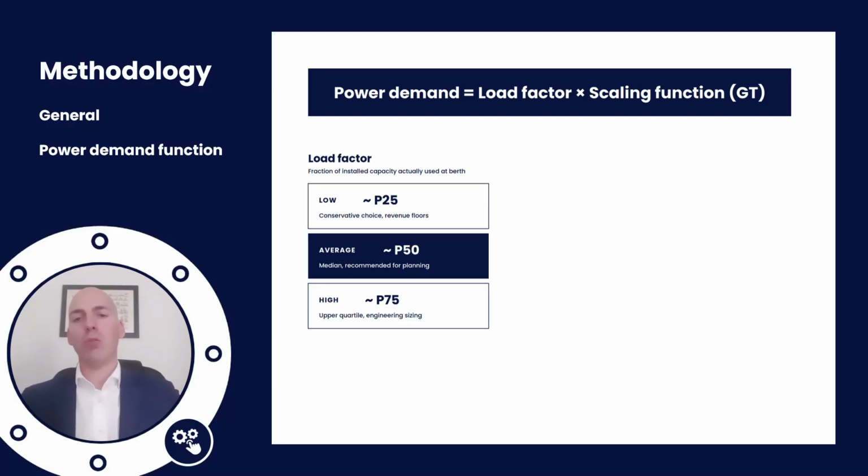You could maybe even argue that if a ship has a certain amount of auxiliary power installed, almost always that is because of safety margins, limit cases, or simply the fact that if we have an engine that needs to provide the auxiliary power, we typically need two, because if we just have one and it needs to be serviced, we cannot power the ship. So typically there's a high degree of over dimensioning the auxiliary power demand.